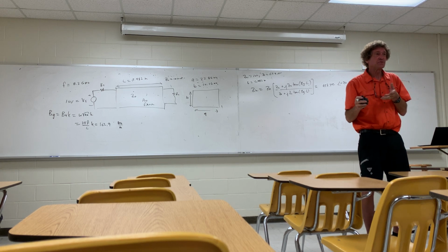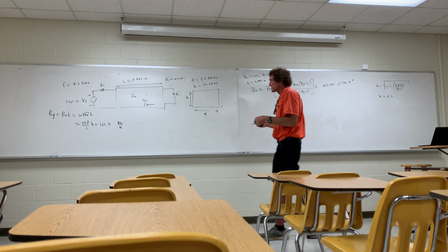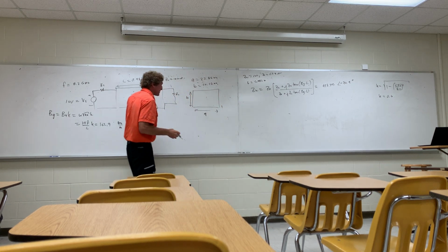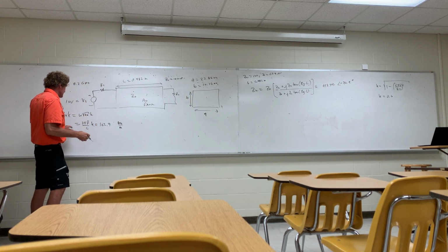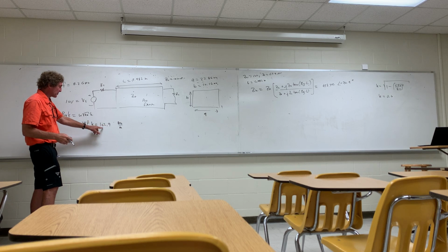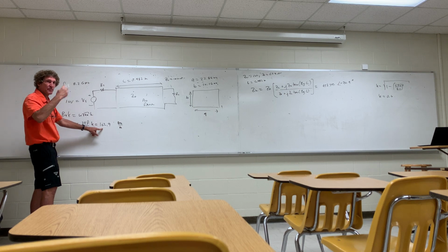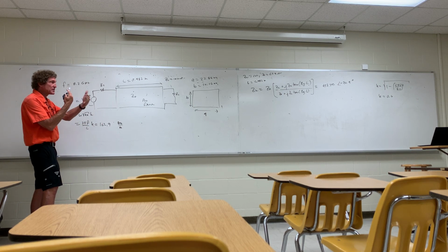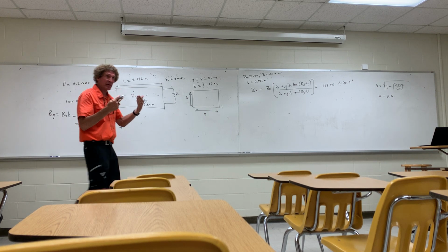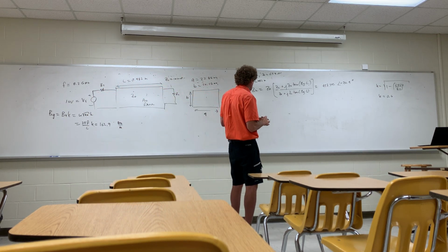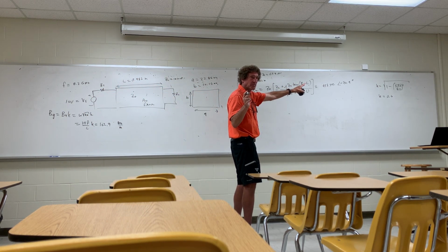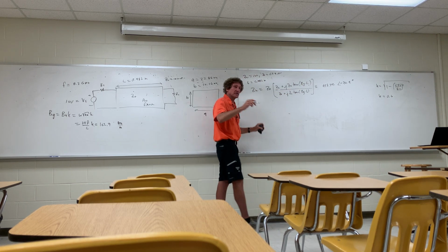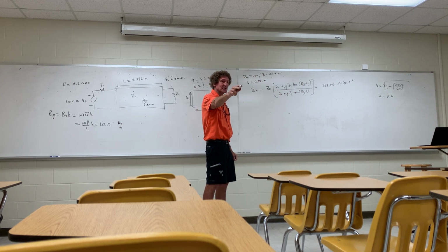The reason there's such a huge change with such small changes is because of the radians per meter. 102.9 radians per meter is an enormous amount of phase change. So very small differences in length, or L times beta, will cause large differences in the value of the tangent function. Remember that. Okay, if that's right, assuming it's right, then the next thing you need, by the way, does this check with you? Because you're the one that brought this up.